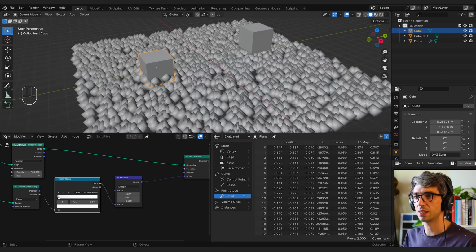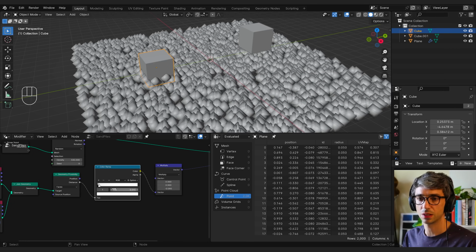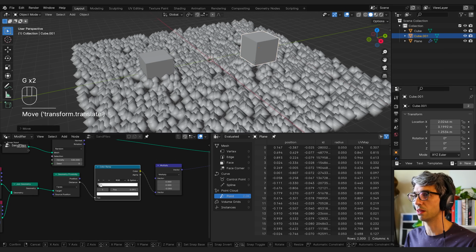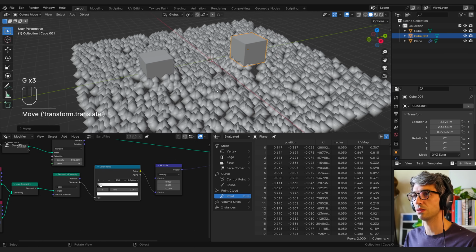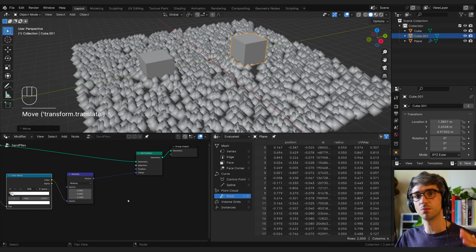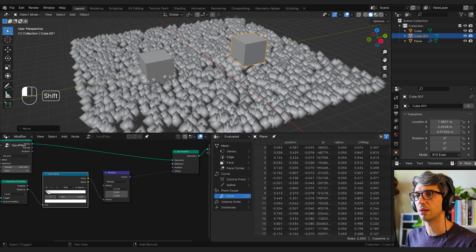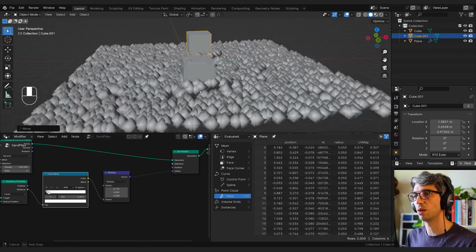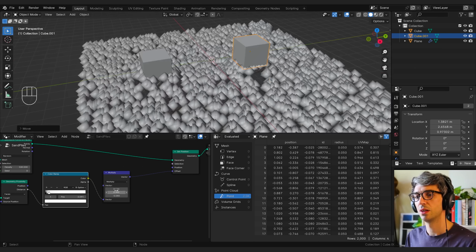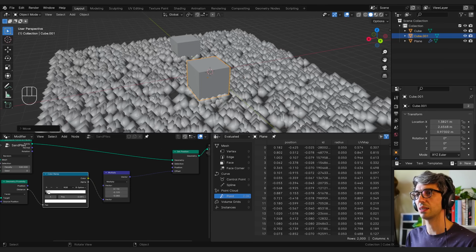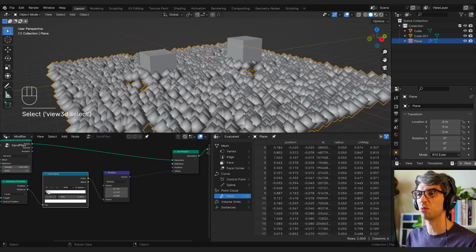And it's a little hard to see because these guys are so big, but we will get to making them smaller soon. But now you can see you're basically changing how far out it raises up. And wherever these guys go, it's going to follow along. So this will be a nice little dynamic system we can use so that the sand piles up. We can also add a little bit to the X or the Y, and that will create a bit of a windblown effect, if that makes sense. So we can put a little bit in both, maybe in the direction of the camera, just so we can see it. And it'll pile up more on one side, which could be really cool.